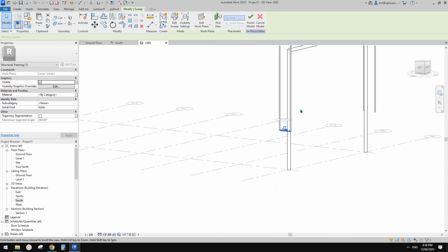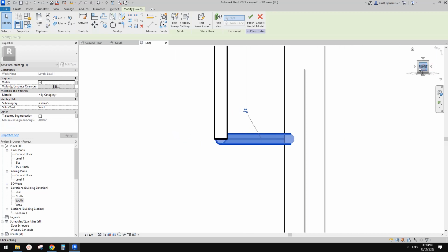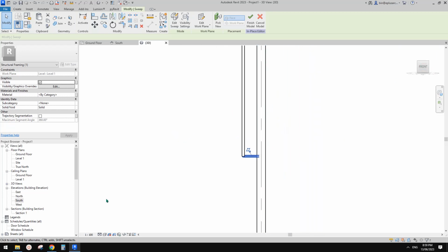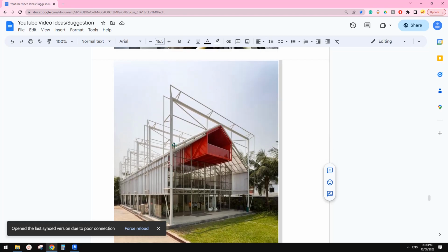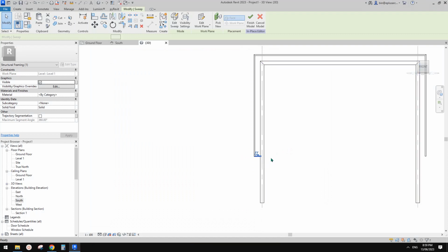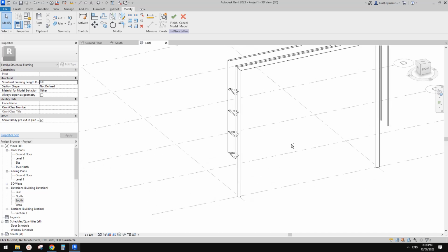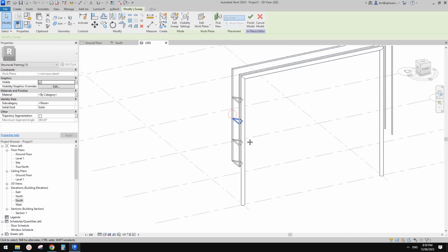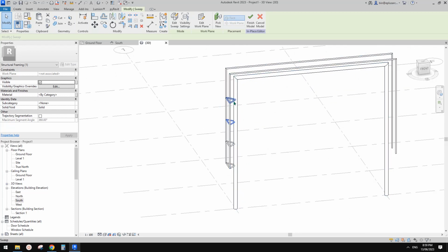So now we have this one, so we can click on the vertical face, like maybe front. Let's see whether or not we can use array. So 1, 2, 3, 4. It looks like every half level. So maybe just copy. Because they are sweeps, you can copy them. So 1.5, 1.5, and 1.5. Apparently this part is not parametric, but it can be quite easy to adjust if we need to.